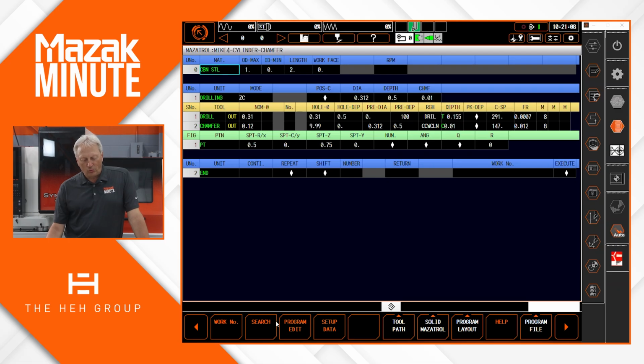I'm going to do a drilling operation. To get there, you're going to hit point machining, high-speed machining, and then drilling. For the mode, we're going to choose the ZC. Give it the diameter, the depth, and the chamfer. The drilling information is going to be 0.31, and it's going to be a 1/2 inch depth.